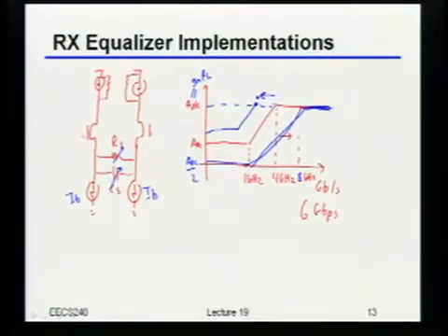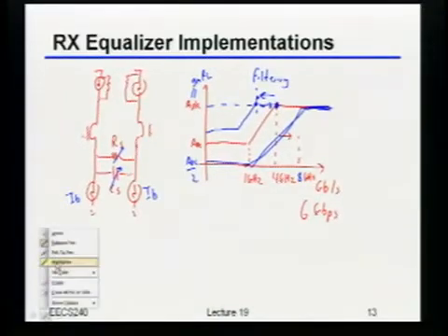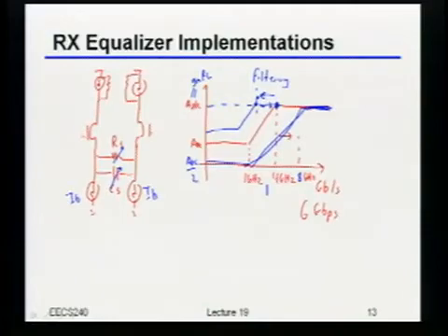Nyquist. Yeah, it's sort of the Nyquist. It's not really Nyquist. It really just means that if I do this, now I'm going to be filtering my input, right? So if you guys remember, last time I had mentioned that you always want to build this thing so that the pole from the equalizer itself lands at the same spot as the actual bandwidth target for your amplifier. This is why. Because basically if you put it too high, you throw away DC gain.